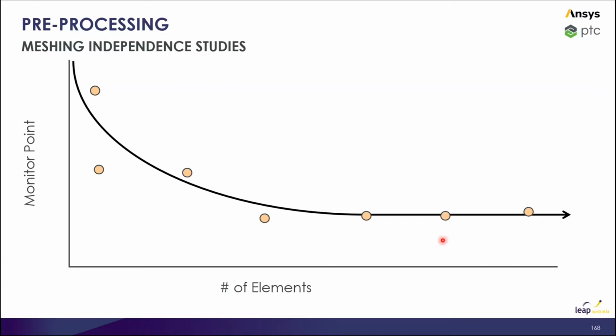Sometimes, though, they can be pretty difficult depending on the flow structures that you've got. In things like the FSAE stuff, you've got finer and finer flow structures that you start to pick up. And then your computational resources start to become a bit of a problem. So you really got to think about what do you actually have available to you. This is an example of that car.